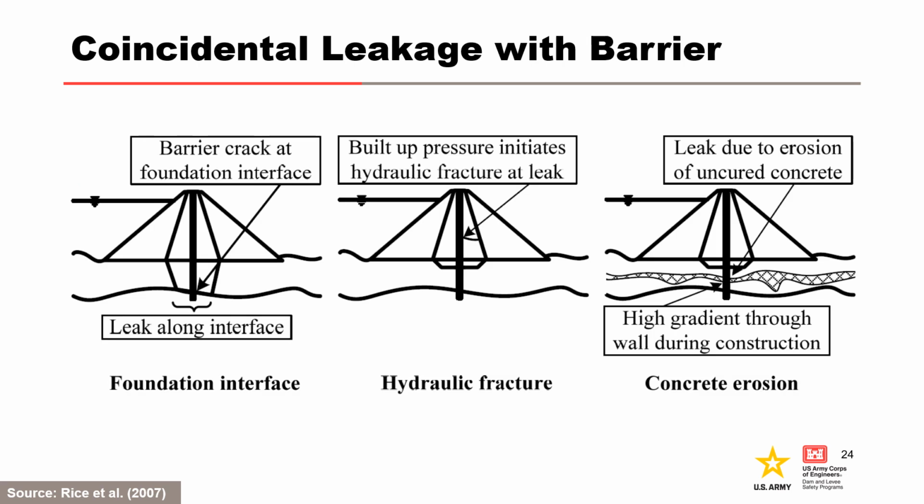In the left figure, the bending moment of the barrier at the top of rock is higher due to the stiffness contrast between the soil and rock and may cause barrier cracking. At the embankment foundation interface, concentrated seepage pathways are more likely due to a concentration of gravelly soils at the base of the alluvium or differential movement between the embankment soils and rock.